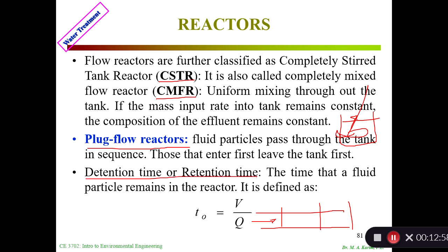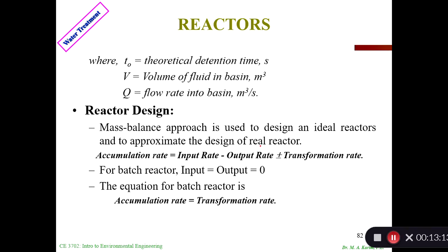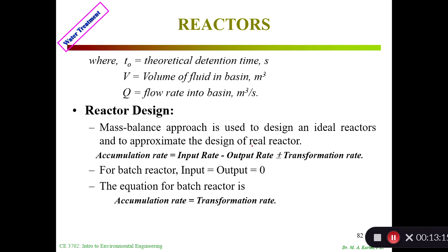And detention time or retention time is the time that a fluid particle remains in the reactor. It is defined as V over Q, right? V is the volume in this case. So volume over Q will give you the time. This is called hydraulic retention time or detention time, HRT. In our topic 5, we'll see different times also, like cell retention time and things like that. Theta is the theoretical retention time, V is the volume in here, and Q is the flow rate into the basin.